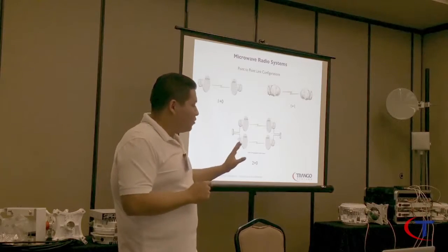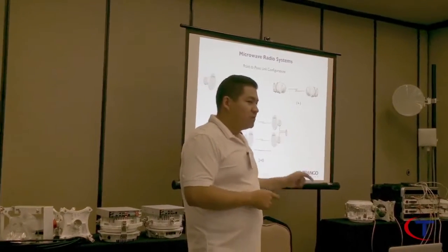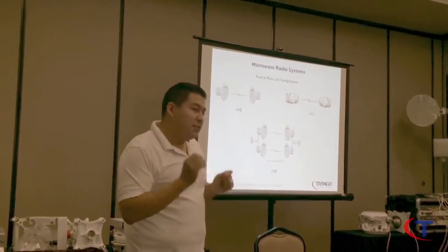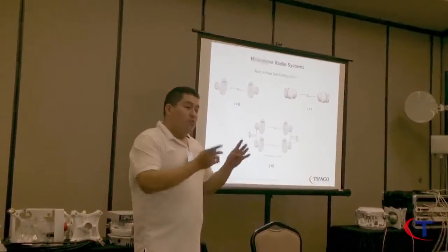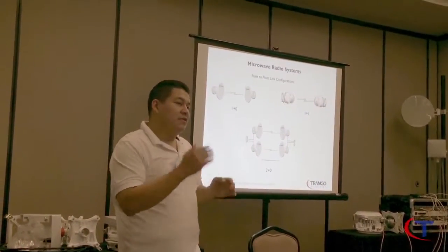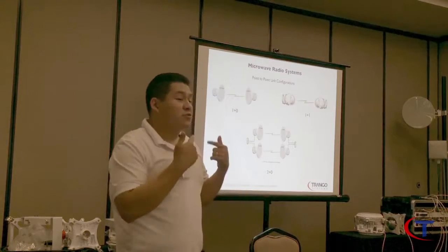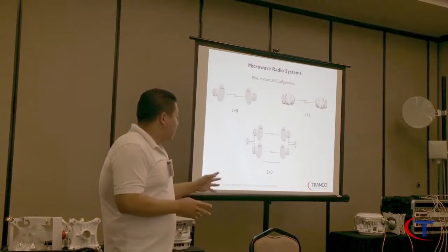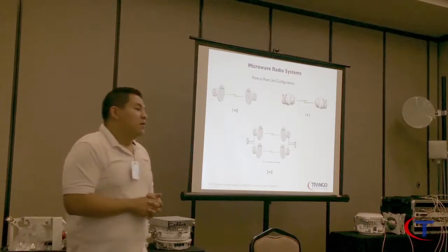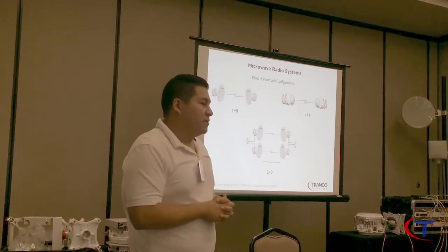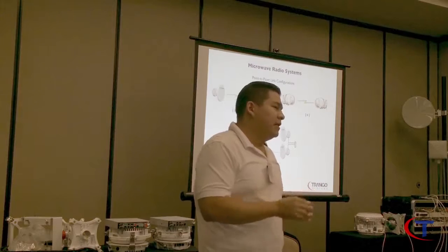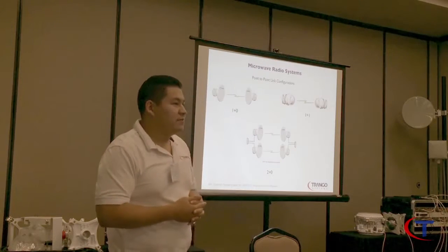So when you have the 1+1 failover, between the radios there's a physical connection, and that is to keep alive literally a bit. When one fails, the master fails, and the slave does not detect the other master unit, it will actually start transmitting. Is that a hitless switch, or how long of a? It's hitless, so it's really fast. I mean, it's the keep alive. It's always constant, so you won't really see it.